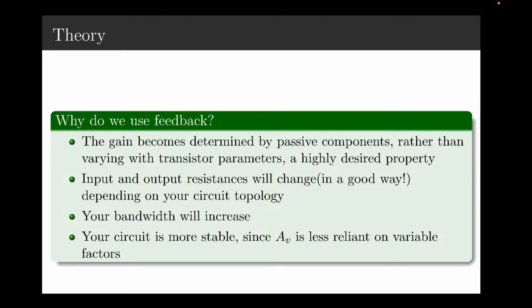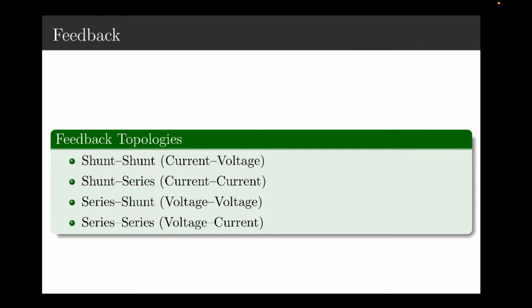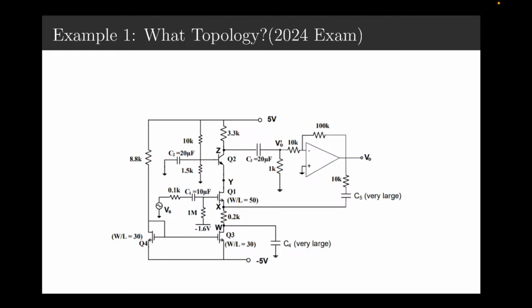And we have RL, the load resistance, okay? So there'd be a voltage divider across this, right? And if your load decreases with the resistance, there's going to be a more even split. But negative feedback says, no, I'm not going to let the voltage change. I'm going to go back and feed some back into the input. Our voltage stays the same, so our impedance actually improves. Depending on what you have over here, depends on your topology, of course, and whether you're outputting a voltage or a current. Okay, so what topology?